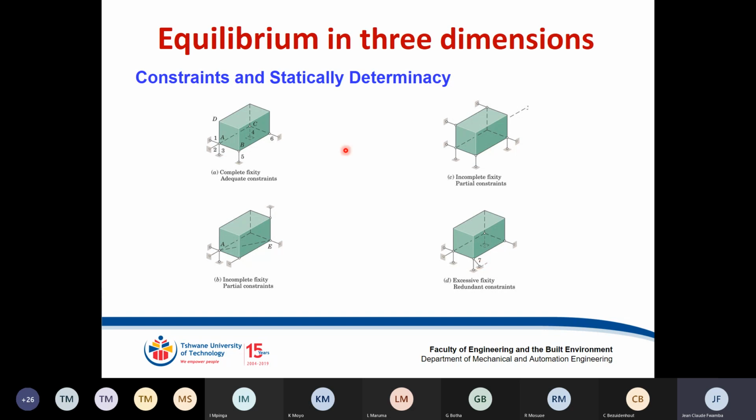Turn your system into statically determinate, which is the position 1, that's the ideal. So in this case, member number 7, constraint number 7, needs to be removed. Then you'll turn your system from being redundant into statically determinate. Right?